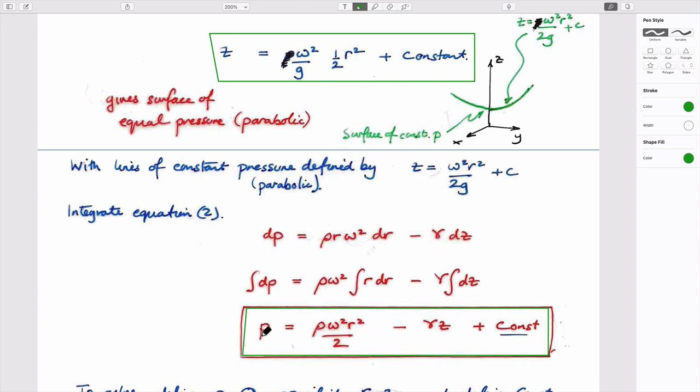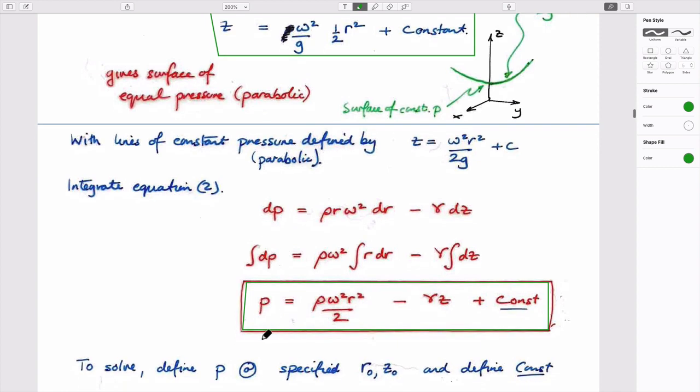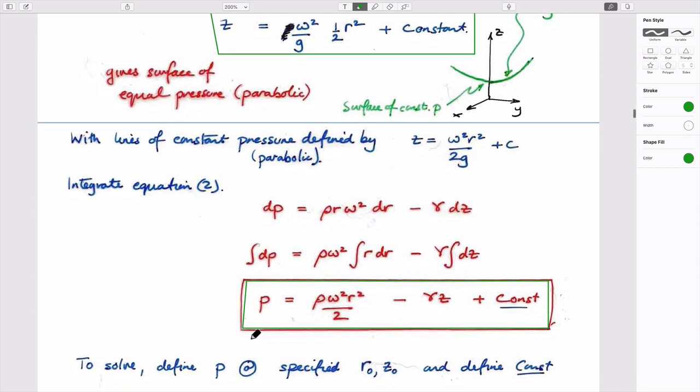And as we go down the fluid pressure in that, we see that the fluid pressure varies in two ways. As we go up or down in the fluid, it just varies as we're in a swimming pool. And that makes sense because we said in this case the vertical acceleration is 0. We're not accelerating upwards, we're just static, and we're spinning around an axis. So that kind of makes sense.